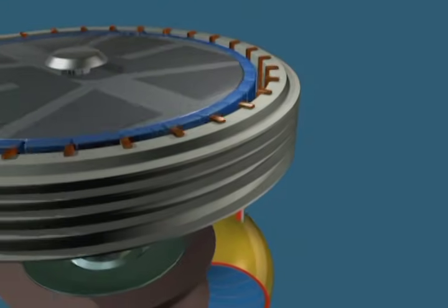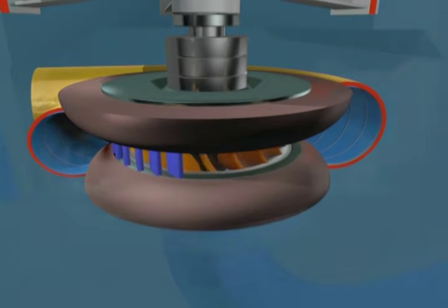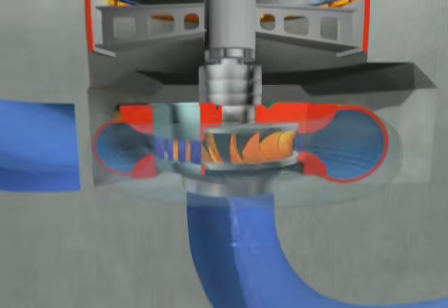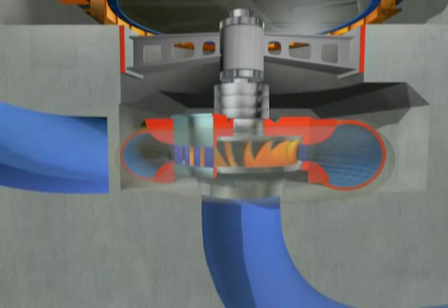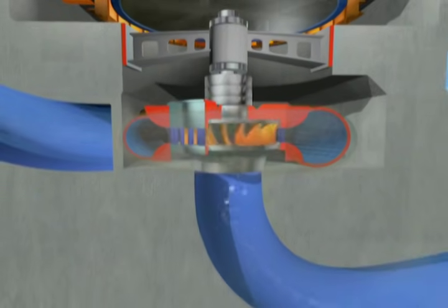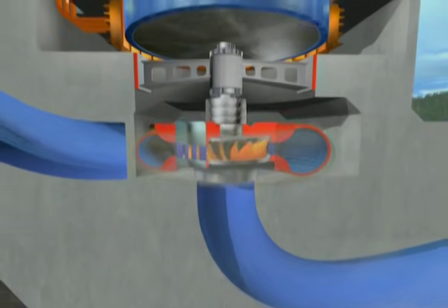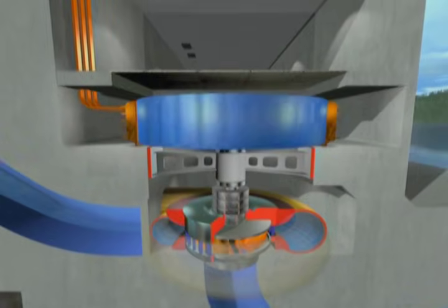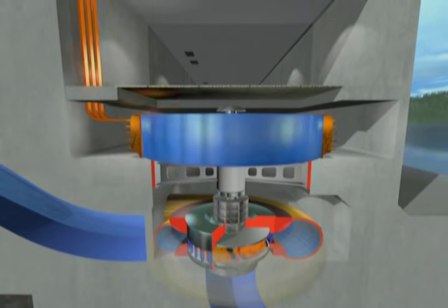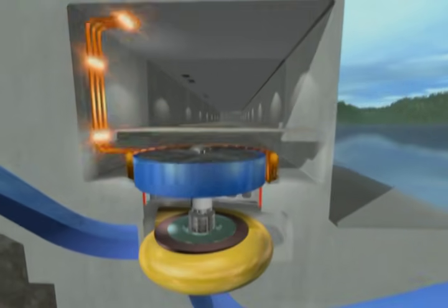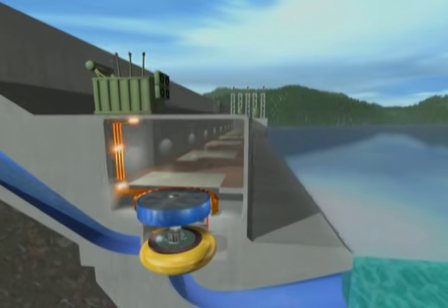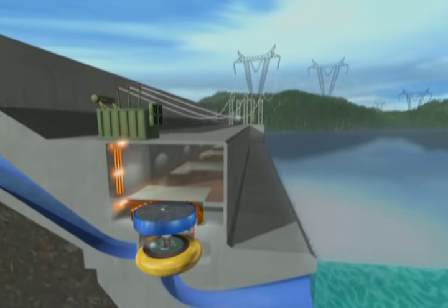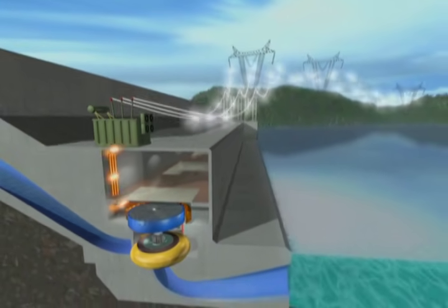With a motor? No, that would certainly not be very efficient. In Quebec, it is mainly the mechanical force of water that makes rotors rotate. The water hits the blades of the turbine, making it turn. To generate electricity, Hydro-Québec thus uses a renewable energy source. The rotating motion of the turbine drives the shaft as well. And since the rotor is also attached to the shaft, it rotates around the stator and makes the electrons move.